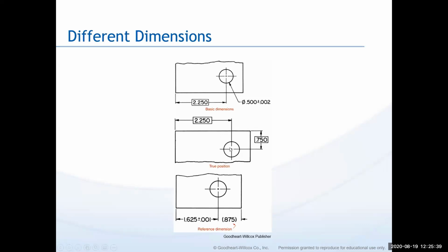So here's the same annotation, but we're saying 2 1/4 over and 3/4 of an inch down to the center line of that hole. That gives us a very accurate location to read. We'll talk a little bit later on about geometric dimensioning and tolerances, which become even more specific about hole location. Now, sometimes you're going to see measurements in parentheses like this.